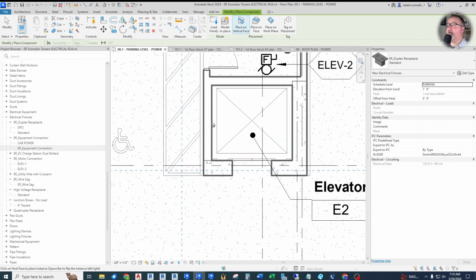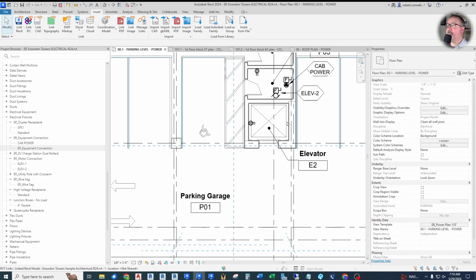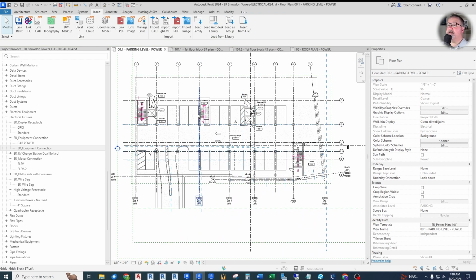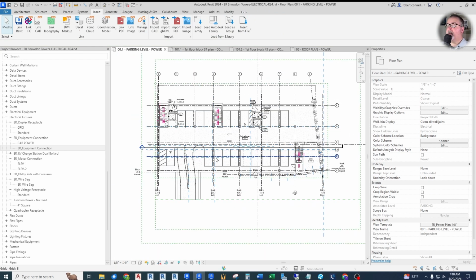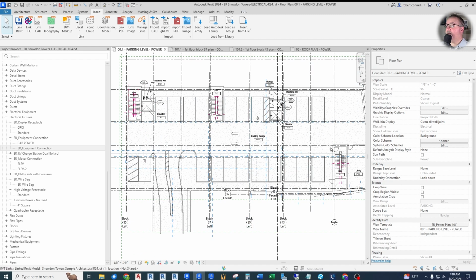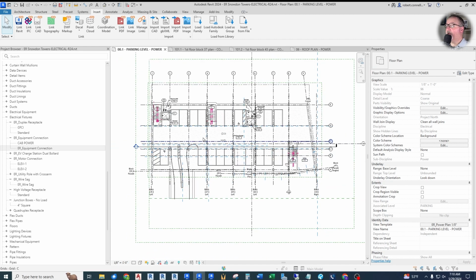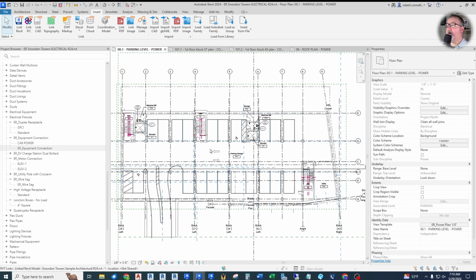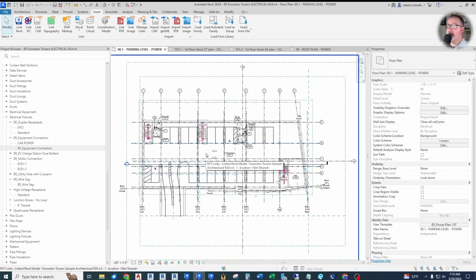So let's get that receptacle in here, just for maintenance. So we're good on the power side. We're not going to put any convenience receptacles in the parking space itself. However, depending on where you are, you may have jurisdictional requirements to get electrical vehicle charging put into multifamily.